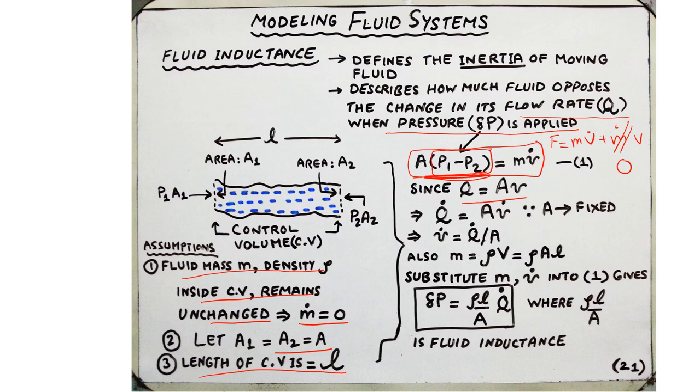So that's the flow rate definition. And then if you take the derivative of the flow rate, we're going to get area times the velocity derivative, or velocity derivative equals the rate of change of flow rate divided by A. By that, we have now introduced the rate of change of flow rate. We have now an opportunity to plug this V dot into this expression and express that in the form of the rate of change of flow rate.